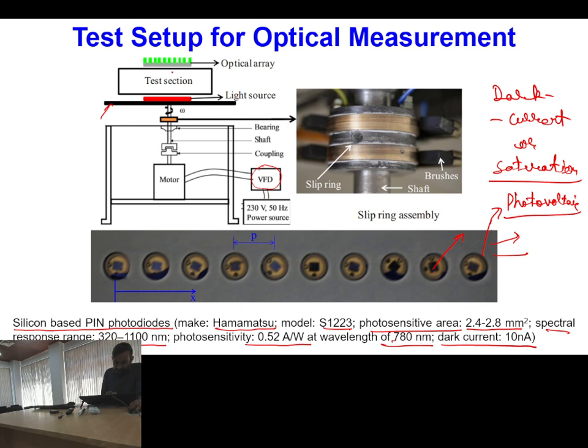Because your entire sensor arrangement is on top of the platform, you have to make some arrangement. The data acquisition system and sensors require power, so you have to transfer power to this system. If you use extension wires, wired connections, then what will happen? Yes, wrapping and unwrapping of the wire. Because of this, a slip ring assembly arrangement is used.